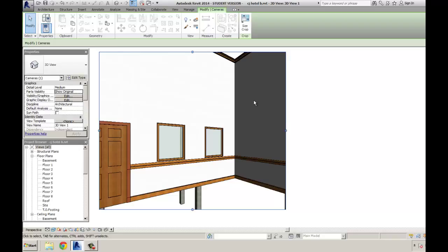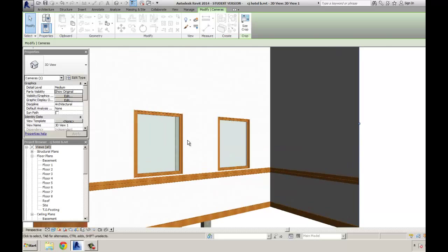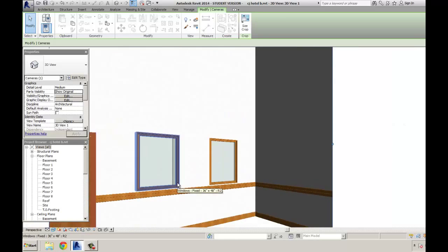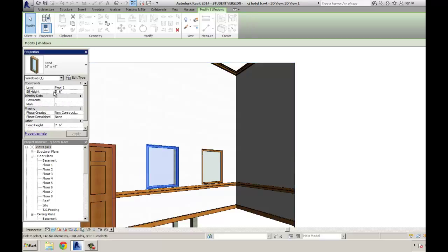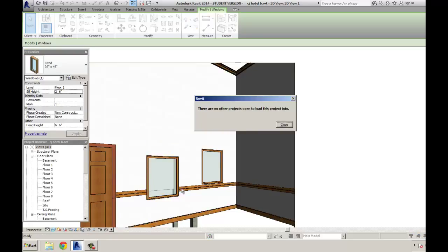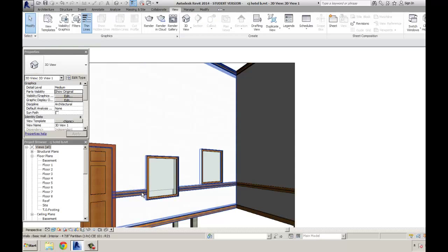So it's just one way that we can customize and create our own wall types by creating any type of profile that you can cut out in wood and use it as basically an extrusion that will actually flow along with the wall and make its breaks where appropriate. I'm not sure why. This is probably because this window doesn't have any trim on it. It didn't look like it cut through that. So if I take this window just as an experiment and put it at 2 foot 6, let me see if it cuts that. Yeah, and see how it cut the chair rail where appropriate to put that through. So it does work automatically, just a nice way to customize it.